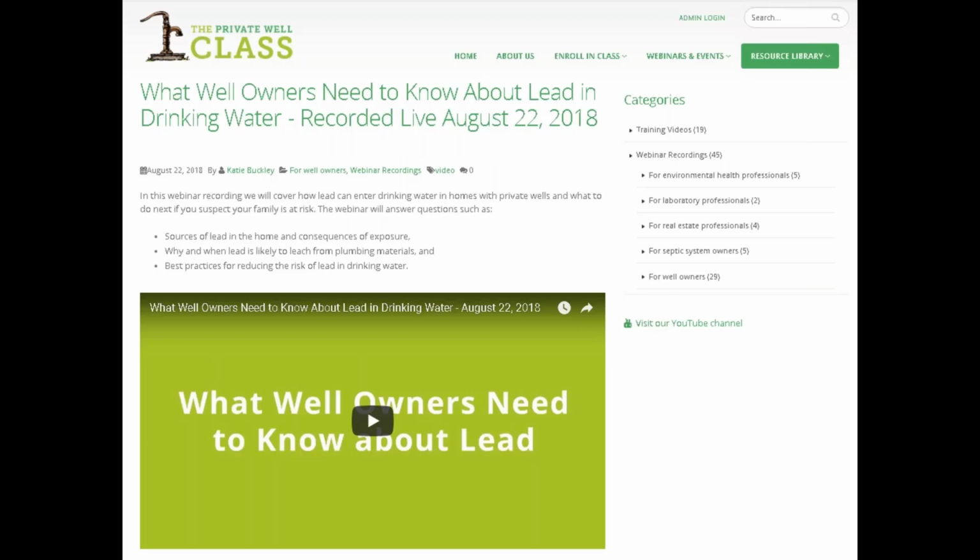Lead is a big issue. Everything you see on the news is about communities and lead service lines for community distribution systems. None of that is going to do anything for any home that has lead or copper pipes with lead solder. So it's really a universal homeowner issue, having lead in your home, as far as lead pipes, copper pipes with lead solder, or galvanized pipes.